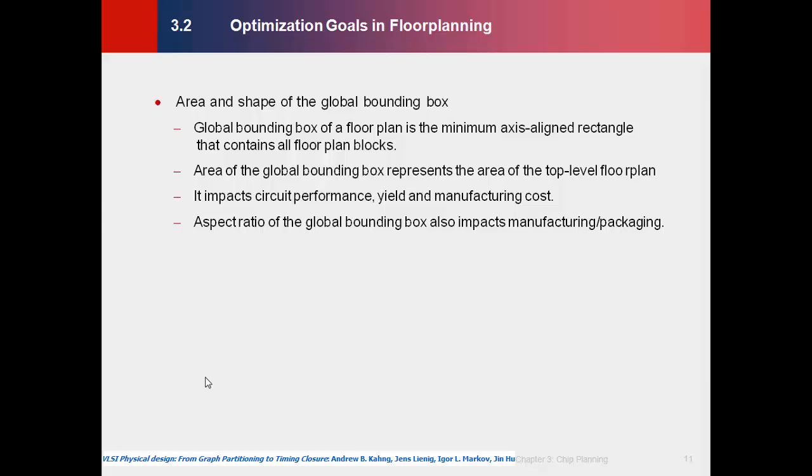And remember that if the top level floor plan is going to have an area of say A square units, then depending on the area, you might be able to produce an appropriate number of designs per wafer. So it is going to affect the yield and the manufacturing cost, and the area also affects the circuit performance, because the more the area, the more the distances between the blocks and the more the interconnections, so it's going to affect the performance or the speed.